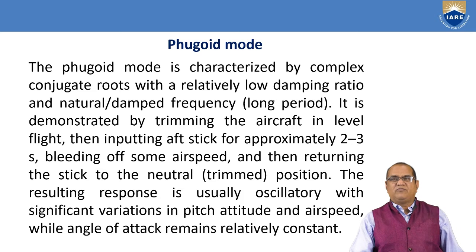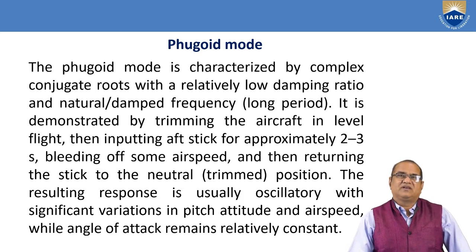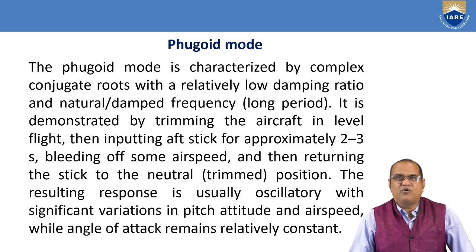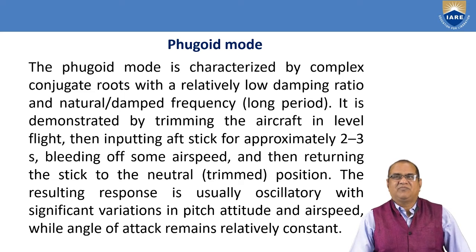Next is Phugoid mode. The Phugoid mode is characterized by a complex conjugate root with relatively low damping and natural, or damped, frequency. It is long period.